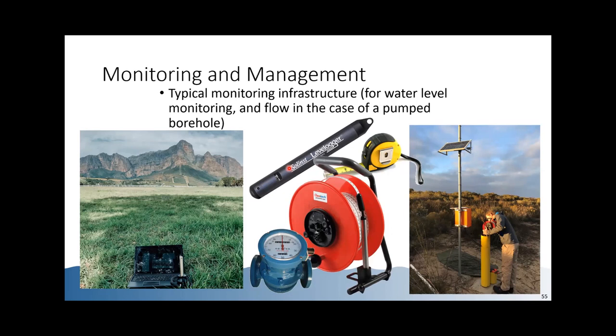We would install this and program it to measure water level measurements every half hour or every hour. And that data can then be assessed, and we get high resolution data in terms of the frequency of the readings to assess how the water level is changing in the borehole. And I'll demonstrate to you some of the conclusions that we can draw from those.